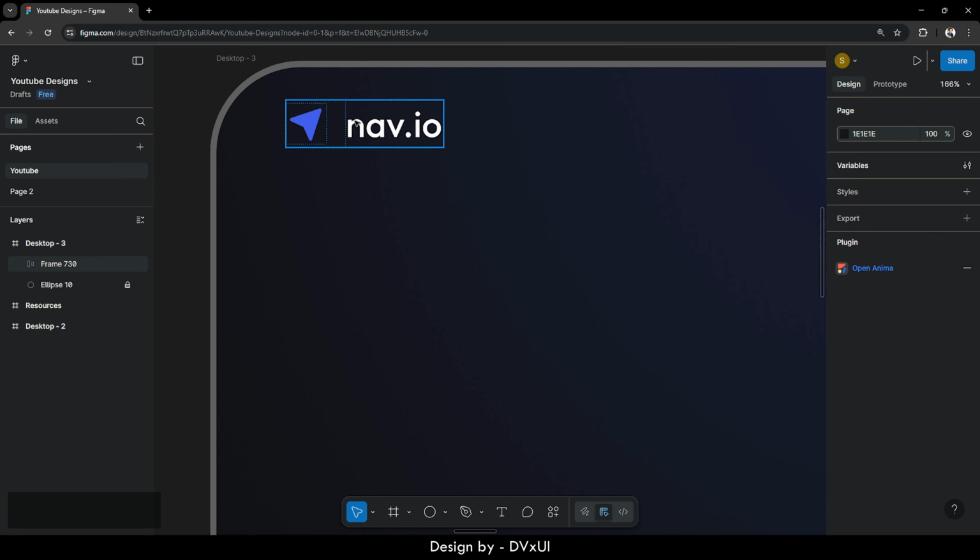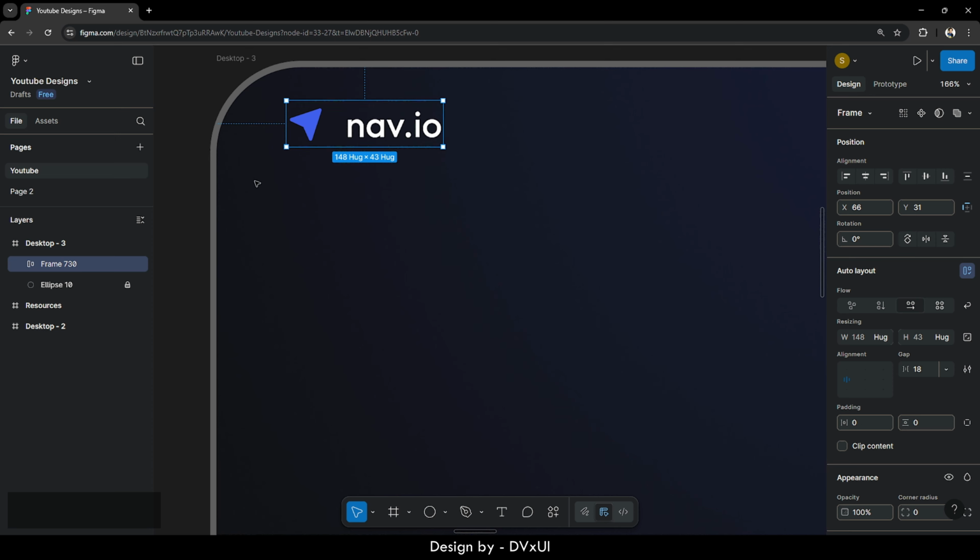So by selecting this element, you will go out of this element, then hold Alt, and you will see the gap is 66. We need a gap of 60. So we will hold Shift and move towards left. Let's see, it is 56. So 1, 2, 3, 4. And now it is 60.